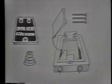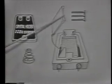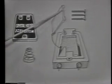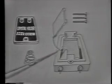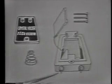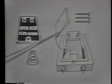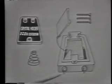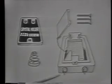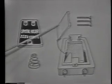The crystal will be placed in the holder between two parallel plates. The plates have an air gap between them, which allows room for the crystal to vibrate. The two plates then are connected to the pins. These are the pins that will allow the voltage to be applied to the plates. And also, the pins will allow the crystal to be connected into a circuit in much the same manner as a vacuum tube. The spring will keep a constant pressure on the plates and hold them firmly in place.